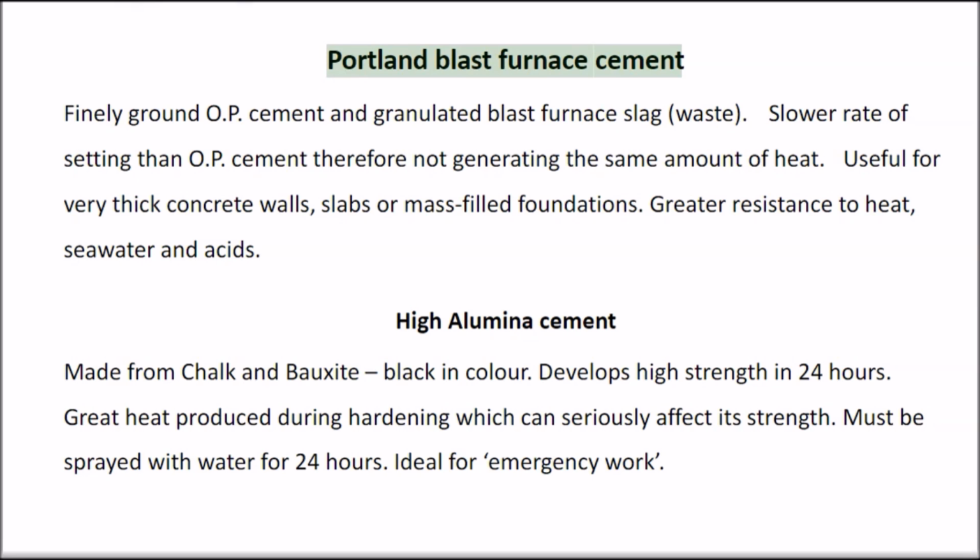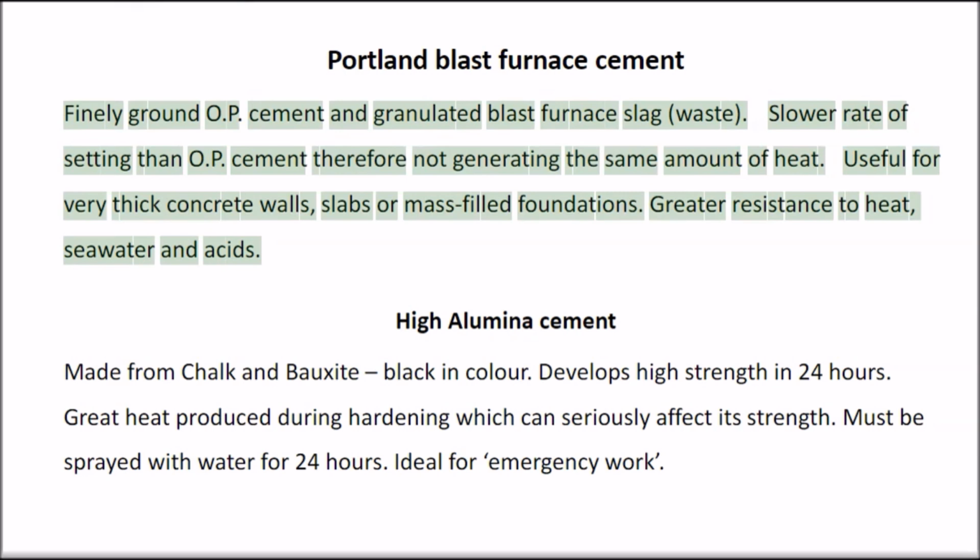Portland blast furnace cement. Finely ground OP cement and granulated blast furnace slag, a waste product. Slower rate of setting than OP cement, therefore not generating the same amount of heat. Useful for very thick concrete walls, slabs or mass-filled foundations. Greater resistance to heat, seawater and acids.